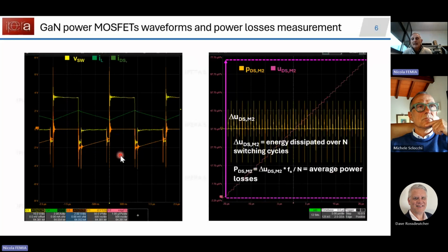Clean waveforms doesn't mean that you have no ringing, because you have parasitic parameters of the PCB, and you may have an undesired impact of the parasitics of the probes themselves. So it's important to select the right probes, the right bandwidth, the right oscilloscope, and to set appropriate channel parameters like the bandwidth, the resolution, the vertical scale.